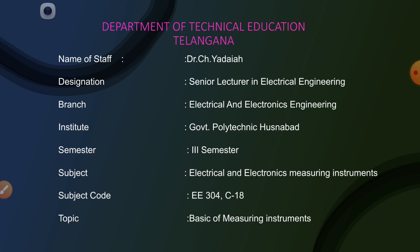In the spring control system, we use hair springs, whereas in the gravity control, we use small balanced weights. In spring control, the scale is uniform, whereas in gravity control, the scale is not uniform, cramped at the start and end.